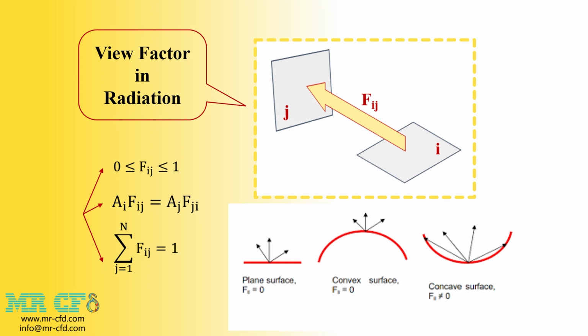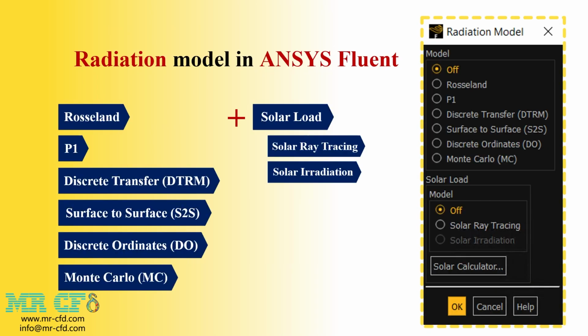Even we can express the expressions Fii, it means radiation between different points of a single surface. Now, if you pay attention to this figure, you can see that Fii is equal to 0 for flat and convex plates, while its visibility coefficient is non-zero for a concave plane.